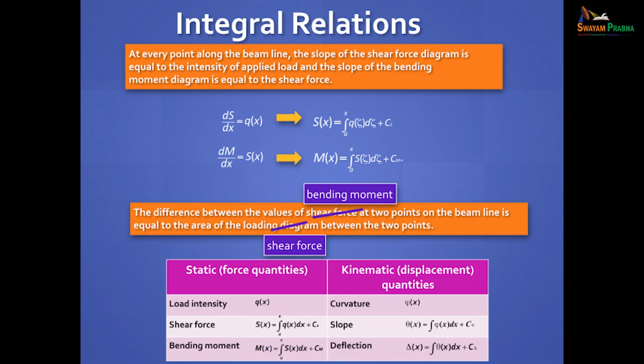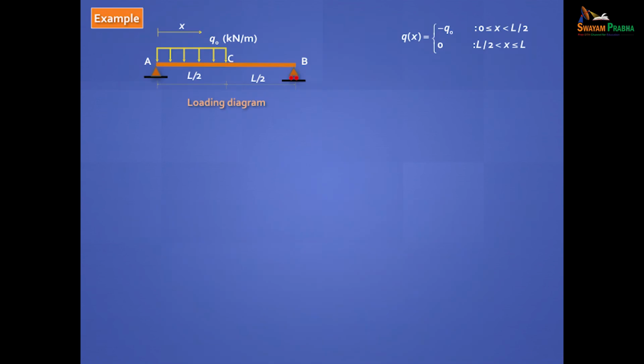Curvature is phi. If this is your starting point, and often this could be a starting point, if you've got bending moment and you divide by EI, you got this. If you want slope, you have to integrate this. If you want deflection, you have to integrate this or do a double integration of this. Similarly here, if you have the load intensity, shear force you get by integrating this, and bending moment you get by integrating this, and curvature you get by dividing this by EI. Are you familiar with this game?